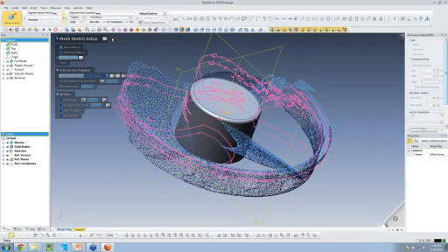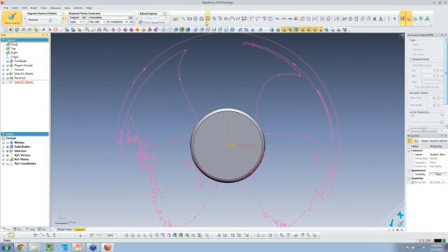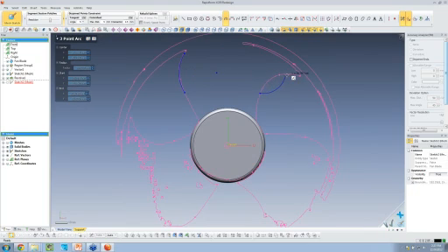You'll see that here's my sketching view once again. And now I can start working on this a little bit further. I'm going to use some of my sketching tools once again, just like I did on that first profile, and I'll reduce my features here. So what we'll do is I'm going to use a 3-point arc. I'll use a couple of 3-point arcs, and we'll just kind of draw this part in a little bit here.